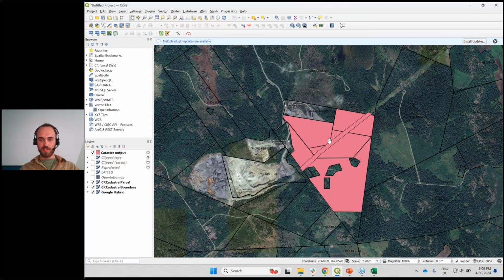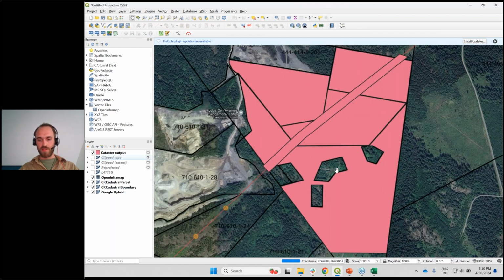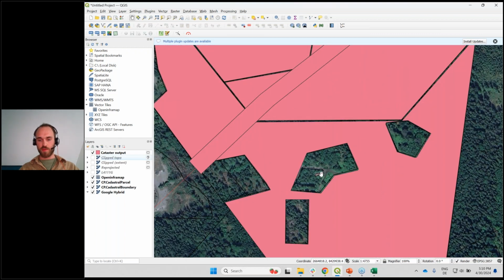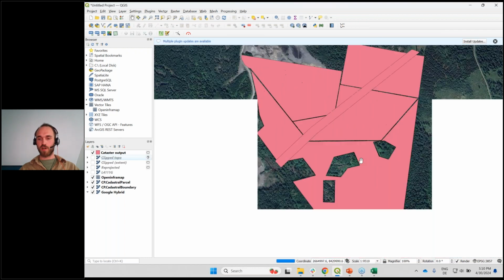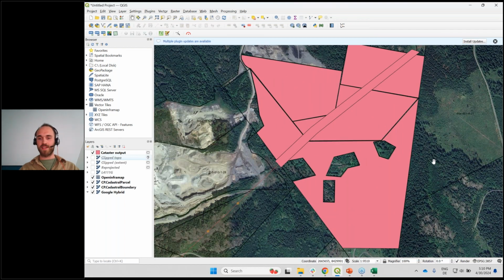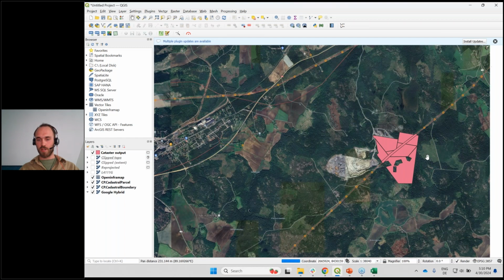And then I also saw that there is an overhead line, basically the Open Infra map, which I didn't include yet. It's an open source layer which tells me, okay, there is a power line passing through here, and we can see the information in the QGIS layer here. And this just helped me to identify the exact area which I want to exclude from any PV modules. And I could also see, if I zoom in here, these are separate cadastre layers with buildings and probably landowners. So I also excluded these in my polygon definition here.